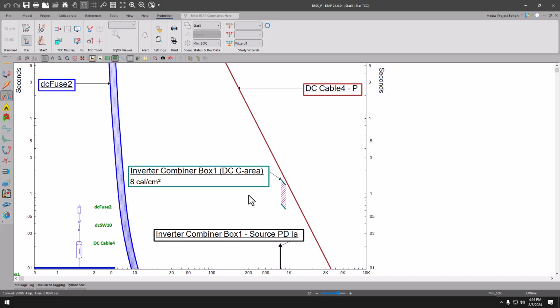And now, as I select my protective device curves, I can see that, for example, this fuse will be basically helping us attain that limited incident energy value. And of course, what helps us here too is that the battery energy storage system has a healthy amount of short circuit current, which is also going to help us reduce those clearing times, right? But again, we have a nice, simple, but elegant way to view this reference curve, even without having to do a formal arc flash analysis.